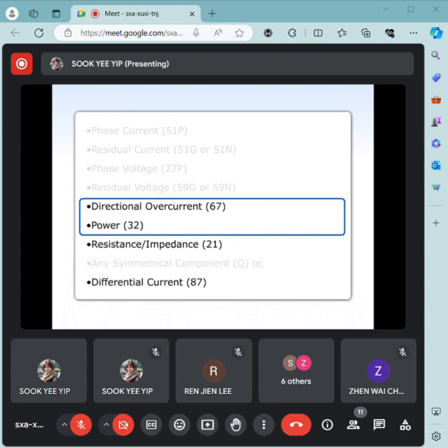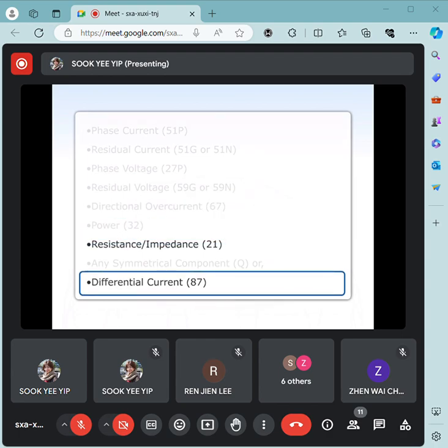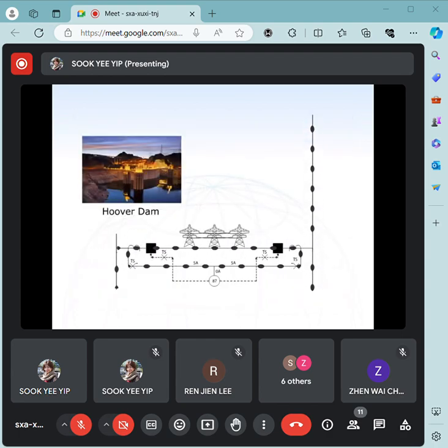The perfect solution is differential protection. Differential protection monitors the current entering and leaving the transmission line and sums them together. If the currents cancel each other out, the differential relay will not trip because the system is either operating normally or there's a fault that's not on the transmission line. If the current leaving the transmission line does not cancel out, the fault must be on the transmission line, and the relay will open both circuit breakers.